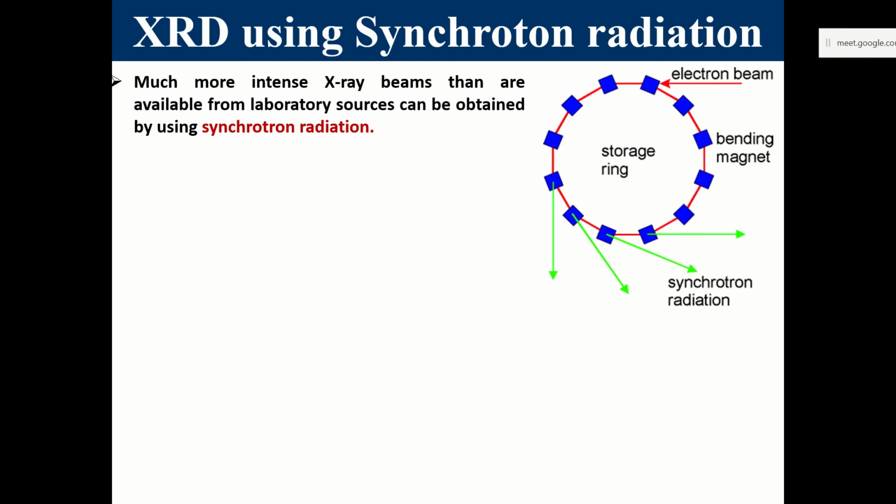First thing is that you should know how to assign the planes, their indexing, how the indexing is done. Then the directions, the crystal direction, that is the perpendicular vector to a set of parallel planes. So that crystal direction is important. We were also able to relate the d values, the interplanar spacing, with the HKL. Then the d value was also correlated with the lambda, that is the Bragg's condition.